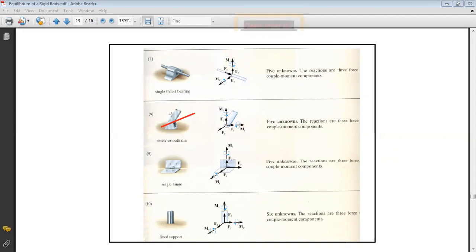This is why I will not develop a resistance moment along X, but I will develop a resisting force Fx. Okay, and in Y and Z I cannot do anything. If you take these two axes, you cannot rotate about them, and you cannot displace your member. So your member is only allowed to do rotation about this axis.